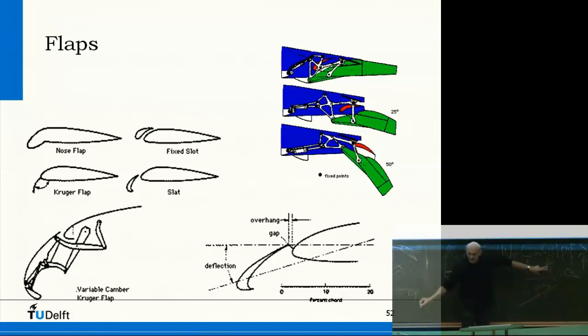So if you put in a vortex generator just in front, higher velocity energy gets into the boundary layer so that the flow will not separate, but will follow the contour. So whenever you see these things, this is a precaution. Whenever the situation might be such that it would separate here, these vortex generators prevent separation. And the same does these slots. It's new air with new energy coming down here.